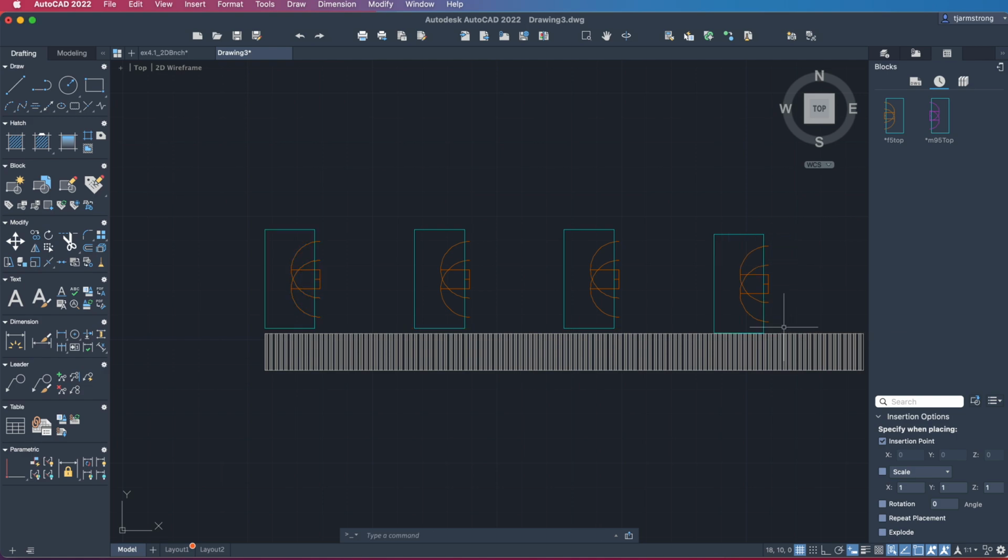Oops, and you can see, I told you I should have used the zoom tool or the ortho tool, because you can see I didn't quite get it lined up correctly. Do what I say, not what I do. Let me just erase that, and I'll just use the move tool, but I'm going to turn on the ortho tool here just by clicking on it down here, and I will just go copy.